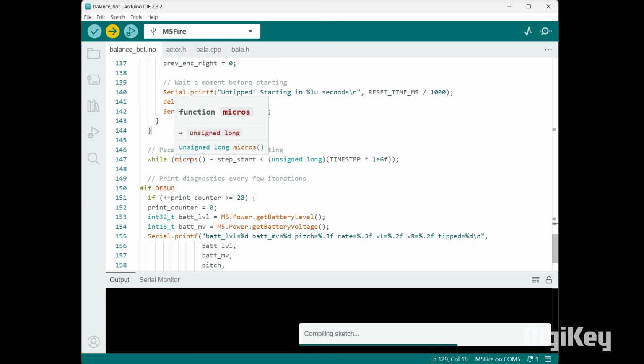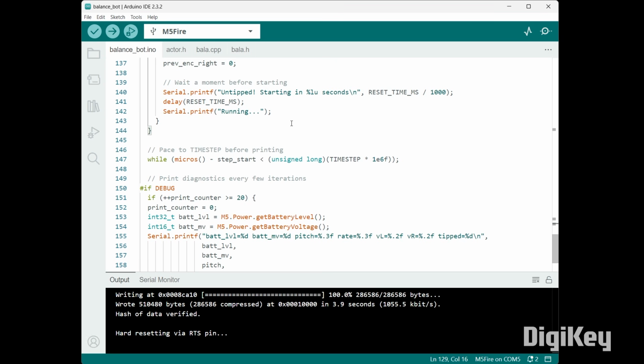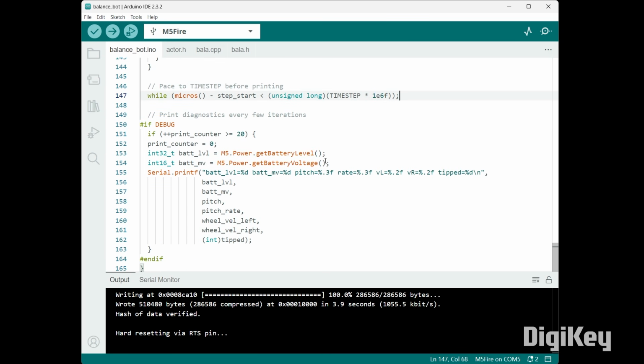We also want to take a look at the amount of time left. Reading from sensors, performing inference, and writing out to the motors should take about 2 to 3 milliseconds, which is well under our 5 millisecond interval time. So we just wait to fill up the rest of that time. You're welcome to do other stuff there, but this is fine for what we're doing on this particular core.